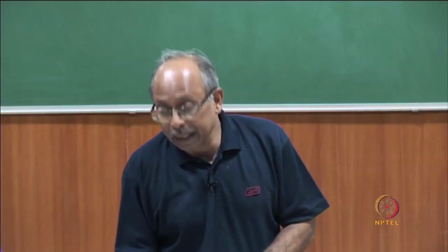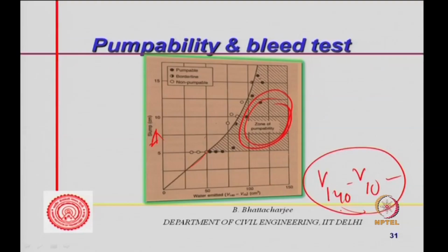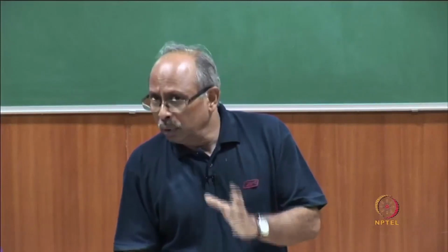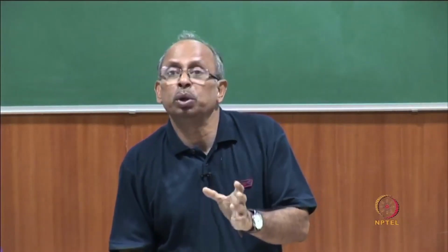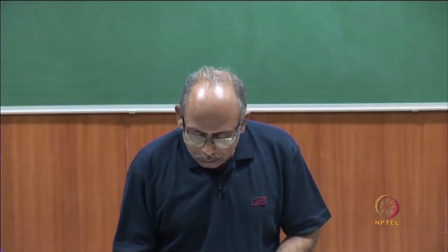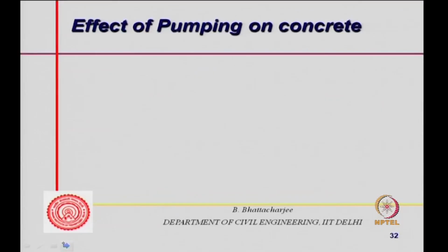So, this zone is readily pumpable. Of course, it is not a very popular test. Most of the people use slump, and therefore, not necessarily always high slump will ensure you pumpability. Well, just to conclude our discussion, effect on pumping of concrete: drier consistency, it tends to become dry.